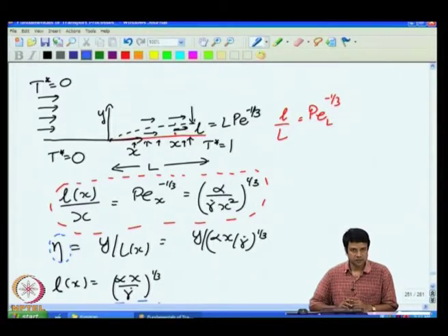At a given location x, the velocity and the temperature fields should not depend upon the total length of the plate, but only upon the distance from the beginning of the heated section. What happens downstream will not really affect what happens at a given location, because convection is going downstream and we have neglected diffusion in the streamwise direction.